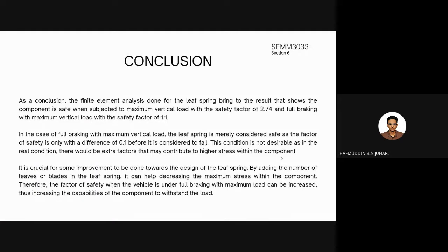So, as a conclusion, the finite element analysis done for the leaf spring shows that the component is safe when subjected to the maximum vertical load with a safety factor of 2.74, and safe when subjected to full braking with maximum vertical load with a safety factor of 1.1.